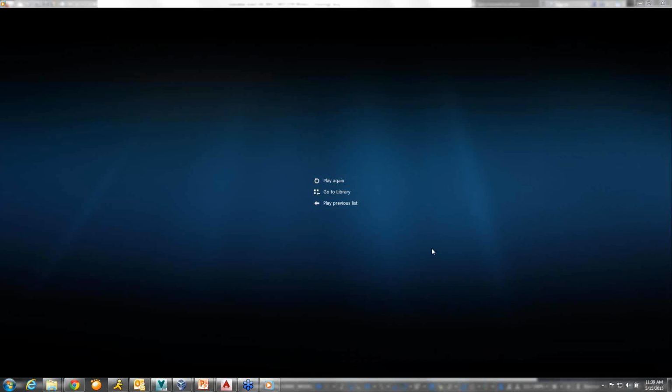If you have a DWF that's outside of Vault, you can just drag and drop it into any folder in Vault, and it'll bring it in as a file that you can manage. If you have a newer updated CAD file in Vault, it'll be published to DWF. So that DWF from Vault, rather than an outside DWF, can be marked up, and then that markup can be saved back into Vault as well. So yes, you can review a DWF in Vault.